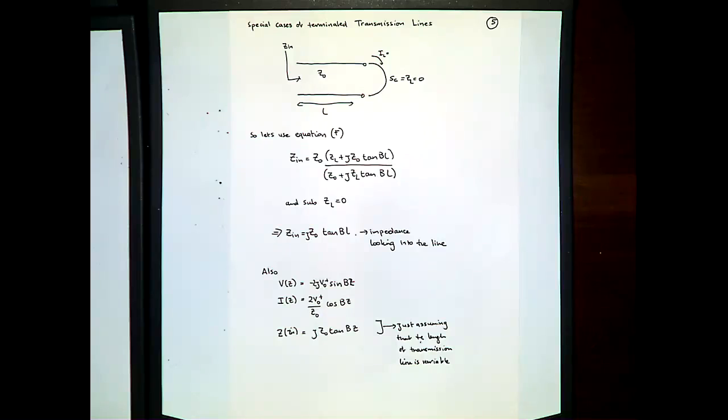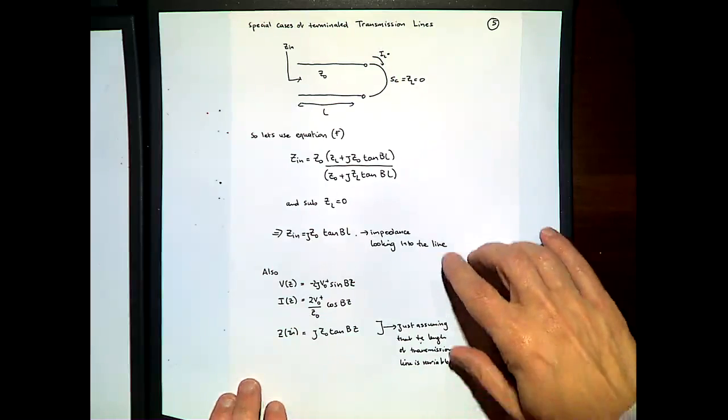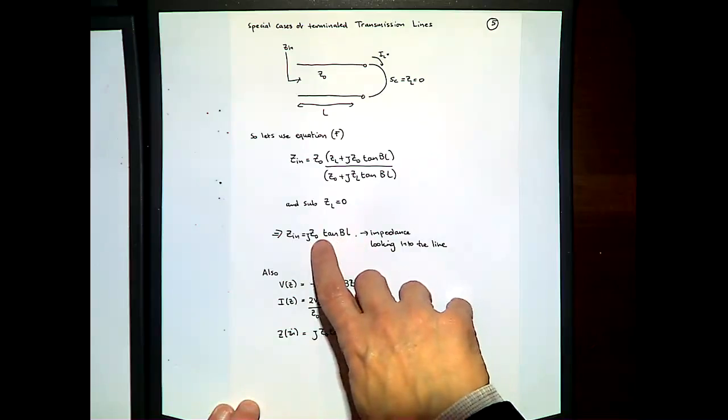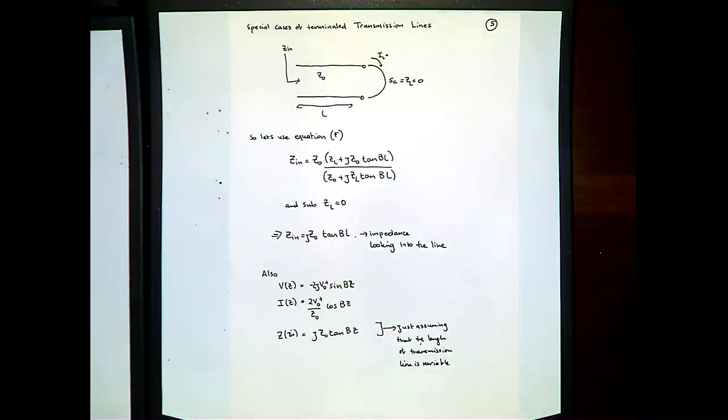Okay, interesting, right? Because what it's saying is that the input impedance of this particular line is complex, but it goes from -infinity to positive infinity. Wow, right? But what's important is I've connected a short circuit, right? It's 0 ohms. Notwithstanding the fact that I've connected 0 ohms to this transmission line, the input impedance that I'm looking into can go from -infinity to +infinity, which, at least the first time I saw it, was like, oh wow, geez.